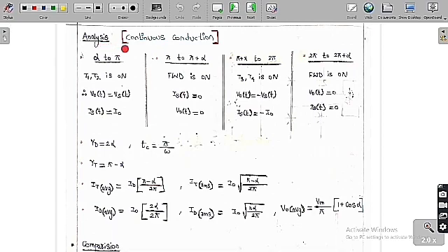So let me do the analysis of this circuit. The circuit we have, which is the full wave bridge rectifier plus the freewheeling diode, is equal to a semi converter. From alpha to pi, T1 and T2 conduct, so the output voltage is equal to the source voltage and the source current is equal to the output current. From pi to pi plus alpha, the freewheeling diode turns on, so the output voltage is 0 and the source current is 0.